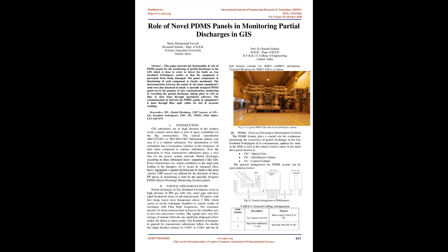UHF sensors are utilized for the detection of these PD pulses, and monitoring is done by the specially designed PDMS, partial discharge monitoring system, panels.